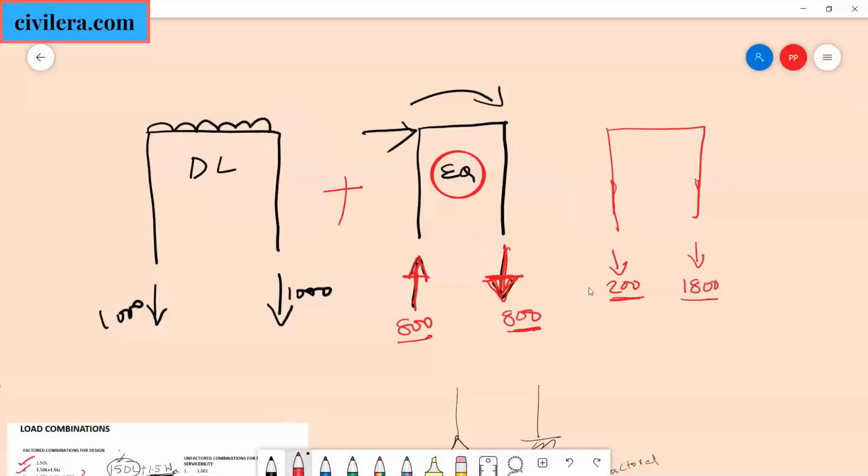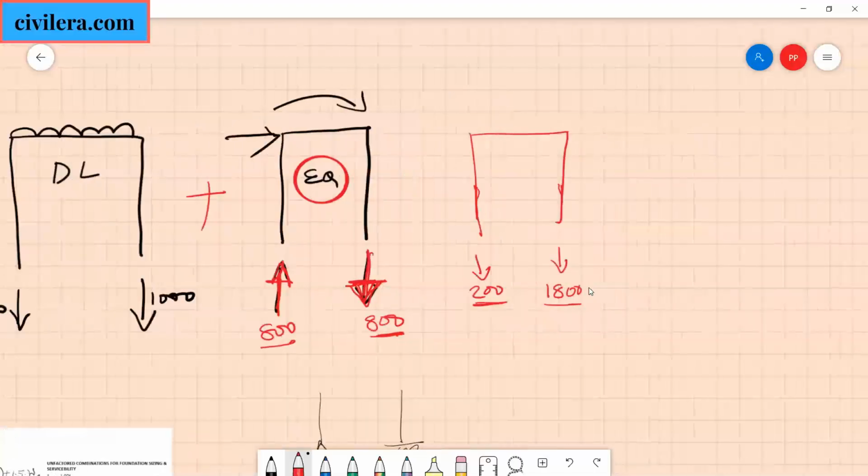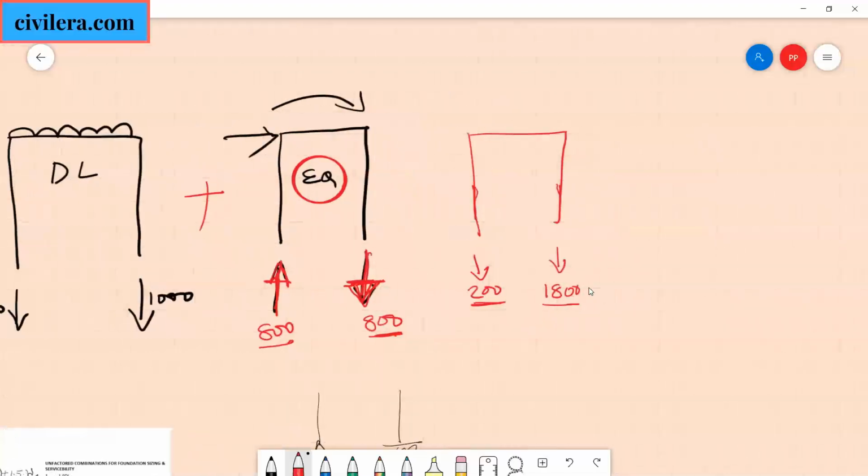Dead load means your self weight of the slab, self weight of every member, then self weight of your screed, your tiles, your brick, your plastering, everything which is permanently going into the building is a dead load. Now, in your design, say the architect and the client told you that your floor is 100 or 150 thickness, and on top of it you are going to put 100 millimeter thickness of screed, and say you are going to put granite on top of that.